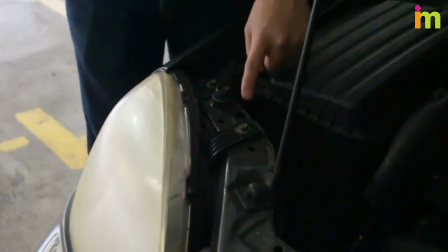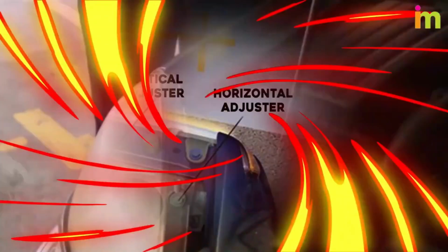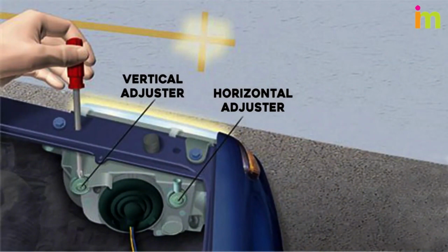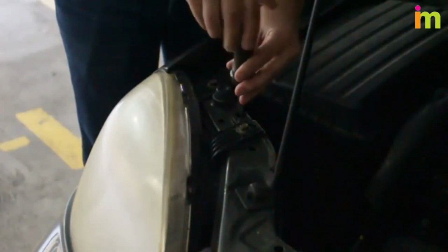Locate the adjusting screws on the housing for each light. Every model works basically the same way: one screw is for up and down adjustments and the other screw is for left or right. You use a screwdriver to manually adjust the angle of the bulb.